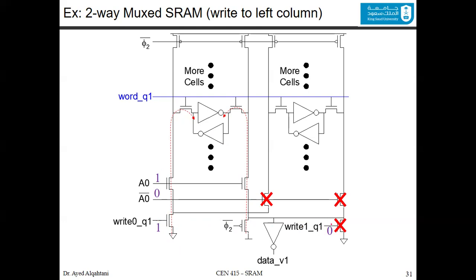If that's 1 and 0, what's happening is this 0, or the ground value here, will be connected to this line. So originally it was 1, 1, 1, and now this one will be 0. If it was the other way around, the other one here will be 0. Since this is 0 and 1, you will write the value here 0 and 1, and it will work because of what we described before. And this way we combine both of them, the read and write. There are many ways to do this, and you can read the book for better ways actually.